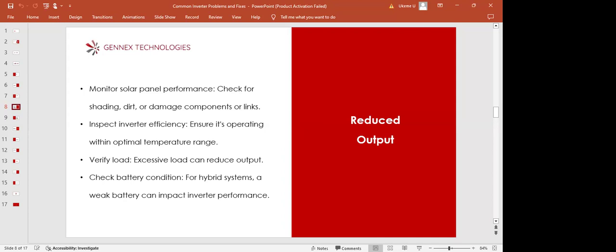That's why you need components that will not make your inverter overloaded, like properly sized circuit breakers or a power limiter at the output of the inverter, so that your inverter works seamlessly. You don't even experience any overload when you have proper sizing of protective devices around the inverter.